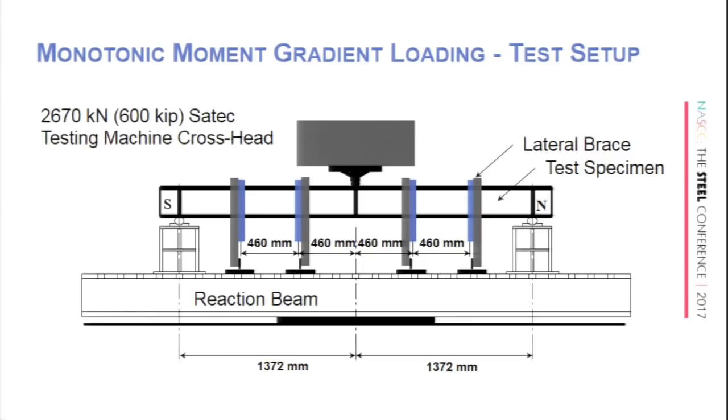So literally what happens is when that beam starts to get load and rotate, those rollers will start to roll up those saddles and then they will roll back down. And they're also greased rollers, so there is very little restraint. If we scribe vertical lines at the end, we can actually look at where the rollers wind up and how much they've rotated.